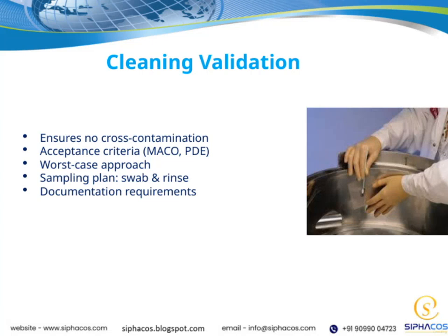Today, I want to focus on how we ensure there is no cross-contamination during cleaning processes. This is critical to maintaining product integrity and safety. We establish clear acceptance criteria, such as MACO and PDE, which help us determine if cleaning has been effective. Adopting a worst-case approach is essential here. By considering the most challenging scenarios, we can ensure our cleaning procedures are robust enough in all situations.